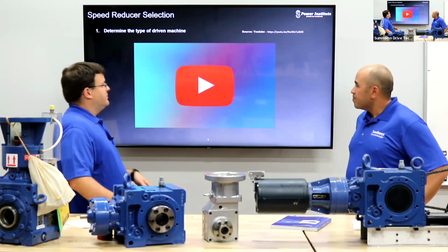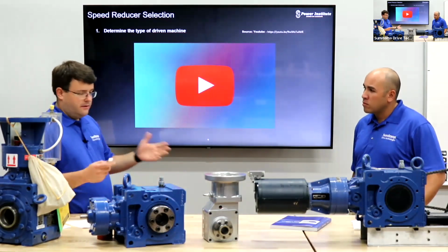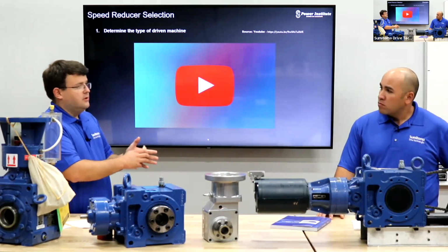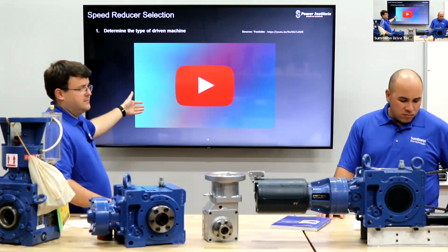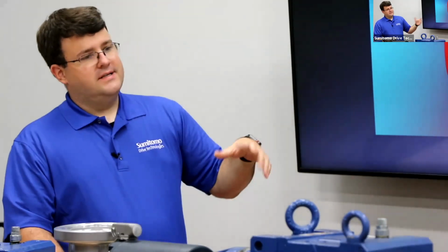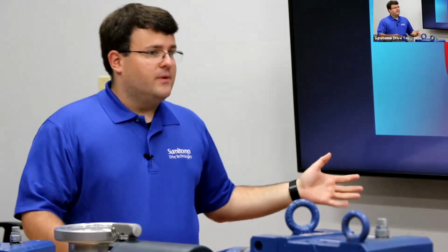Let's start the selection process. There are a few factors we call service factors or safety factors, however you want to look at it. Essentially, you have your base selection, but then you always put a little bit on top of it to allow for and prevent failure with these other types of unknowns, if you will. Yes, we know how much weight is moving, but if for whatever reason that little scoop in that example grabs more than the next one, we have to be prepared for that.